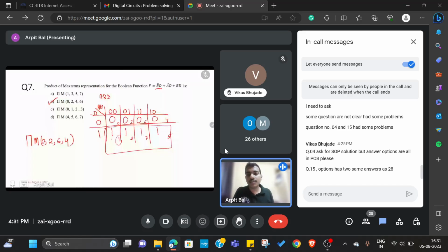Whatever value a position holds, you should have a practice of marking that value, because in bigger equations it becomes complicated to track which box represents which value. So just make a small 1, 2 or such number and try to resolve it. Here also we did the same thing, and we observed that 0, 2, 4, 6 are the max terms.